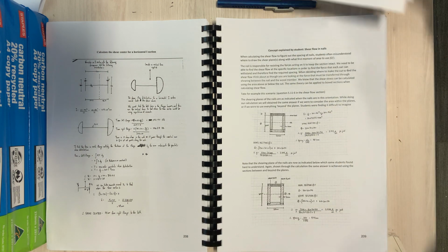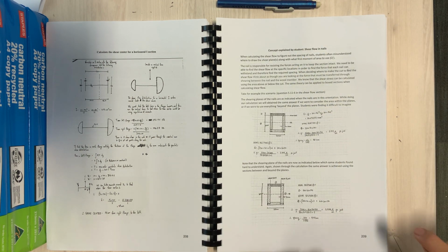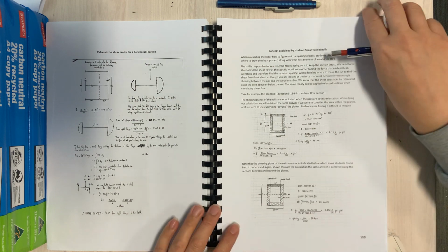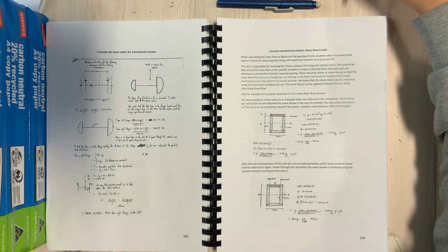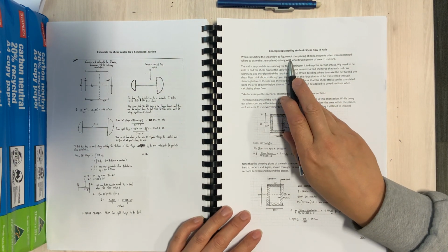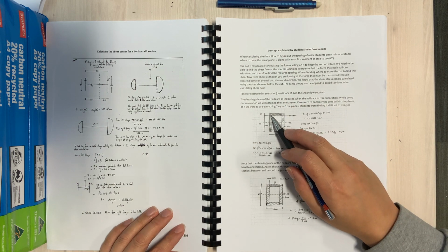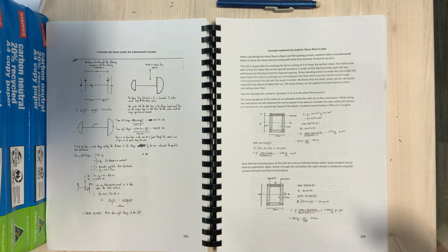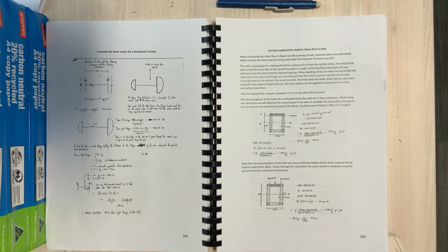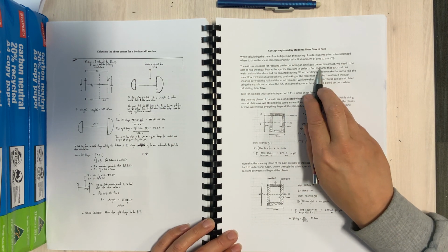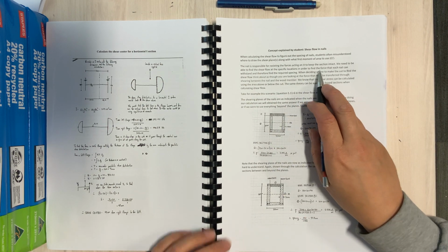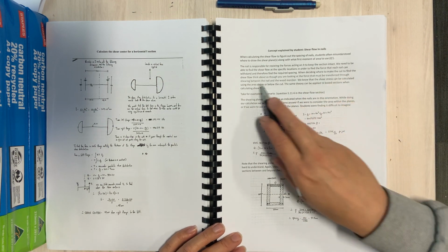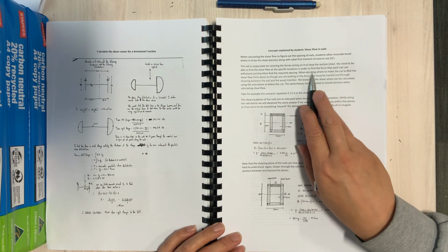Okay. So the next problem that students sometimes have is the shear flow in a nail. When calculating the shear flow, the nail or the adhesive keeps the bits of wood acting compositely. The nail is responsible for resisting the forces. To keep the section intact, we need to be able to find the shear flow at these specific locations in order to find out the force that each nail will withstand, and then you can work out the spacing.